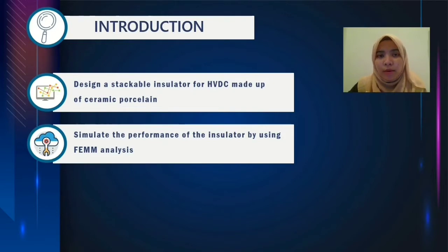For example, the abnormal voltage is transient overvoltage, where the transient overvoltage is a sudden rise in the voltage due to the lightning strike and also the failure of the switching operation. The lightning strike can be immediate, and it can damage the equipment as well as the component. So the insulator needs to be able to suppress the sudden high voltage from the lightning strike. And we also need a good insulator to be able to withstand the inconsistent frequency from the switching operation.